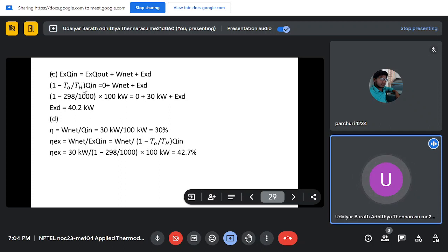So that work is the maximum work which you can get from the heat which you are supplying. Assuming it's all ideal and reversible, this is the maximum amount of work you can get. So this is the ideal case, but our process cycle is not ideal. This cycle has some irreversibility and some friction, everything.